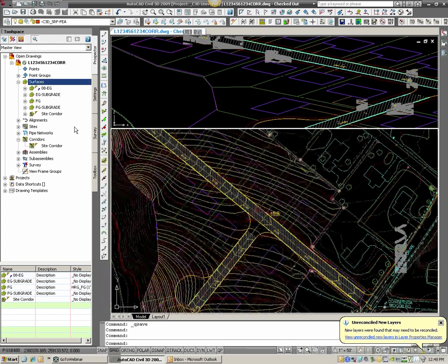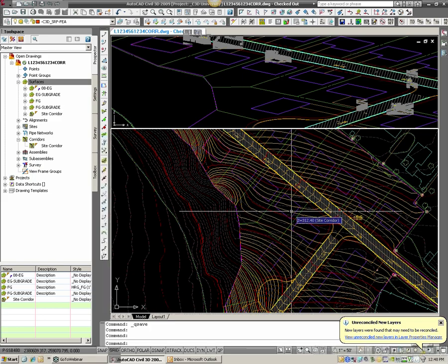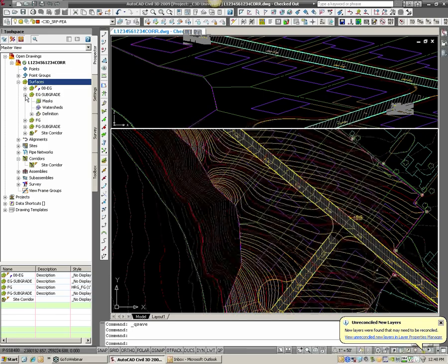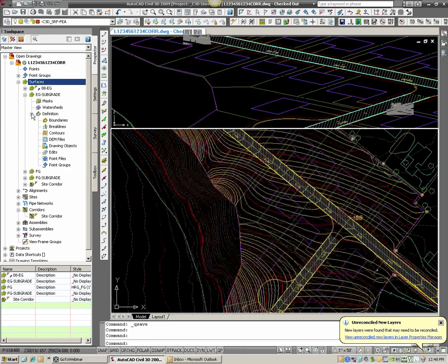So on this project, let's say it had 8 inches of topsoil they found out. You look at your geotech logs or the soils books, and I'm just going to assume right now that this has 8 inches of topsoil. You'd have to look into that. It could be more, it could be less. I worked on projects that have had no topsoil because it was so rocky. It's right beside a quarry, but no topsoil.